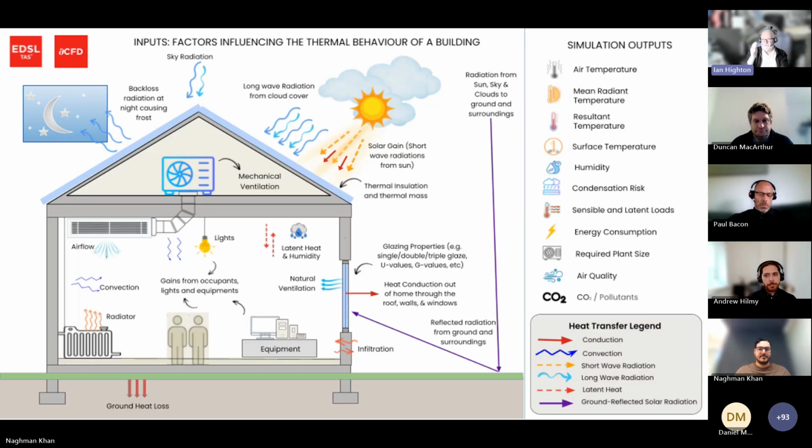So if the building's cooled down overnight, for example, and the structure is really quite cool, the heating kicks on inside the space, obviously for the occupants. You've maybe got some early morning sunshine coming in, and because it's thermally massive, you can actually get heat coming into that fabric component from both sides.